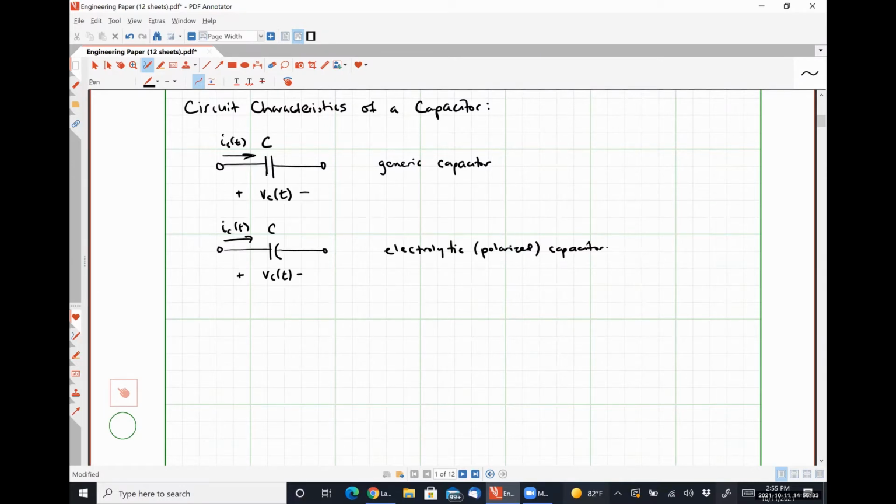If you ever see that the plate has curved up or something like that, that's an electrolytic capacitor that is burst. Okay, so it doesn't actually release any fluid or anything like that unless you were to physically break open the canister. But applying that wrong polarity voltage causes a physical deformation in the structure, which causes it to no longer act as a capacitor, and you have to replace it.